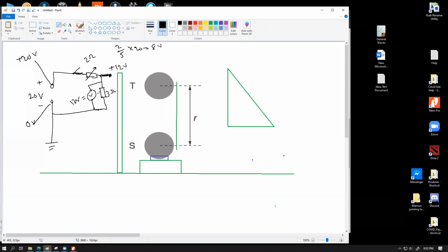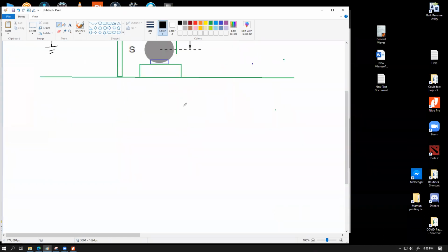Okay, sir, understood. Sir, this is pretty elaborate, but I've seen variable DC supplies and stuff. Why not use those? You can use a variable DC supply. Works. You can connect a voltmeter across the variable DC supply, connect one end to the ground, and use the other end. Beautiful. I did not use that shortcut version because I wanted to show you exactly how this can work with a fixed supply. The variable DC supply can work even much more easily.